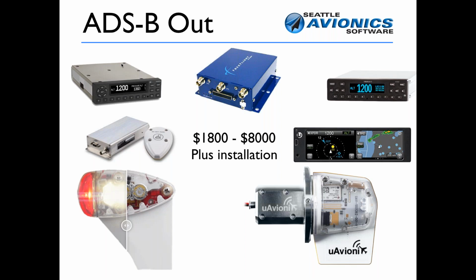I mean, that's basically all it is. It's a transmitter. It gives location information to the ground or to other aircraft in the area. It doesn't receive anything. It doesn't know about weather. It doesn't know about traffic, and it has no real need to talk to your iPad. So if you just wanted ADSB out, the Garmin stuff is totally fine. If you want to use ADSB in, an ADSB in system made by Garmin simply will not work with FlyQ or with a large number of other applications on either iOS or Android.